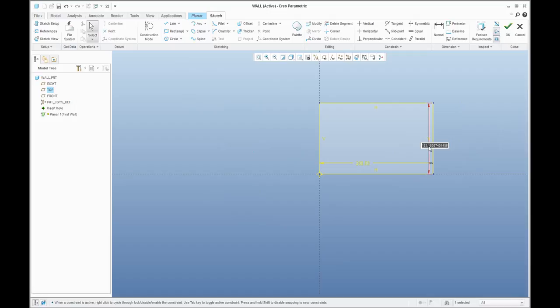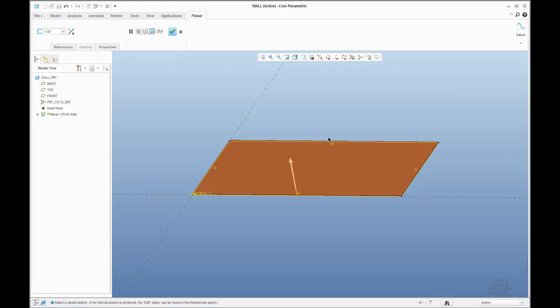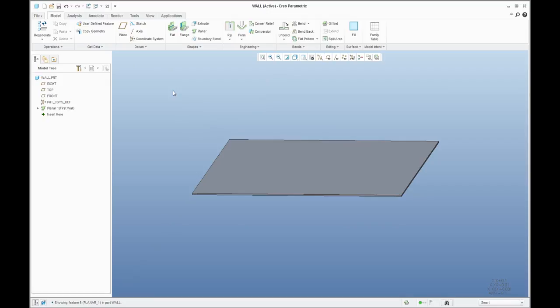Edit the sketch and set the custom values you need, and with the confirm icon the system will switch to the dynamic preview, and you can specify the thickness of your Sheetmetal. I've spoken about that. Now I'd like to show you and explain how to use the flat feature.